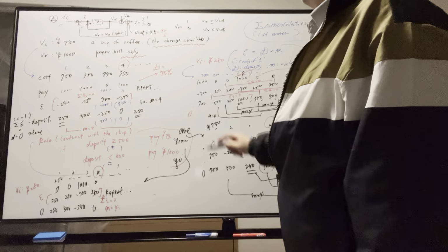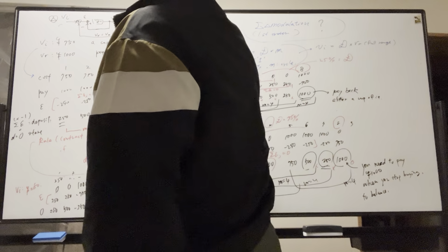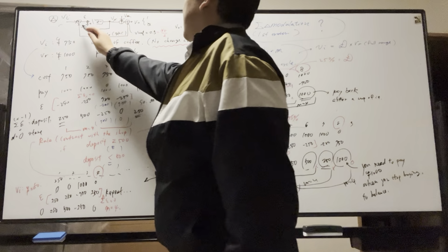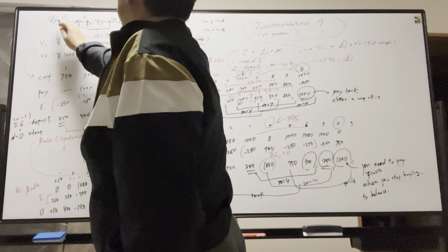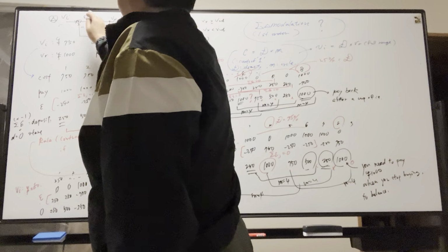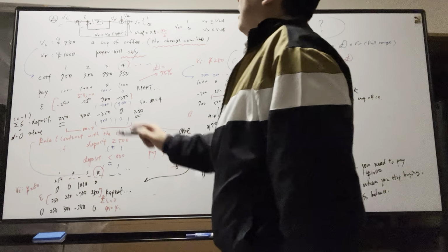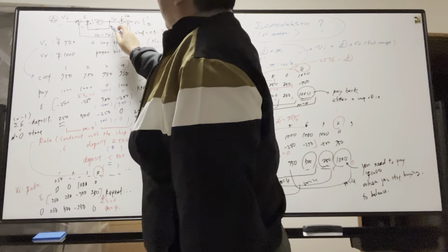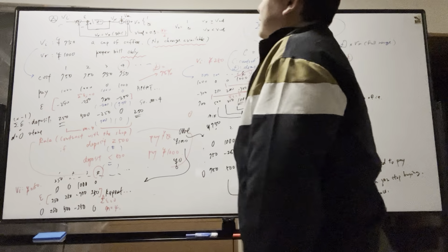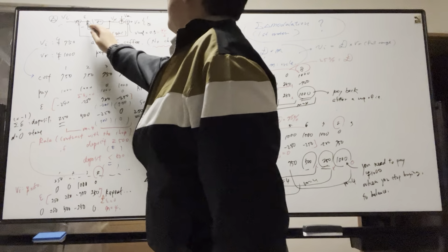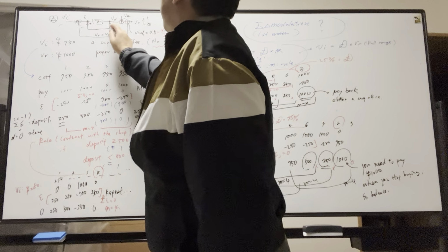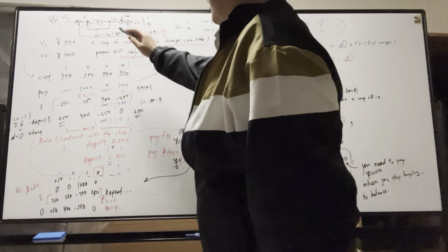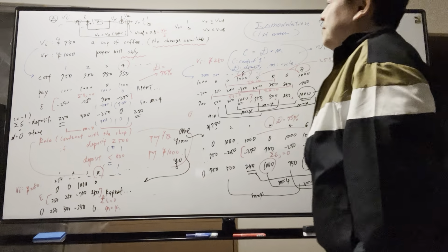And VR equals 1 represents exactly the same value for the AD conversion analog value, and subtracting it from Vi makes the error. Then the error, delayed one step, makes Vx and goes back to be added to the next error, accumulating and making Vo.